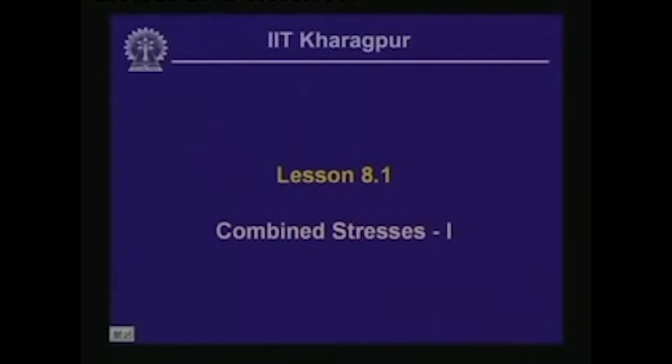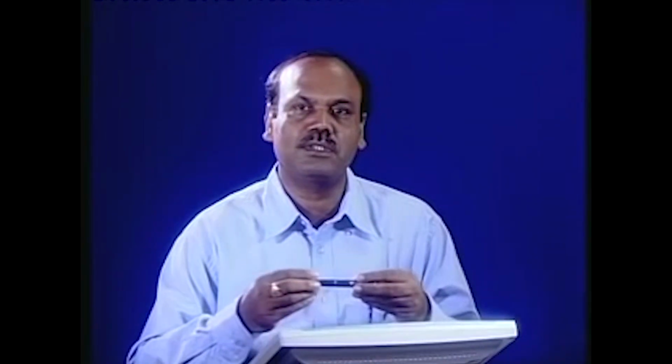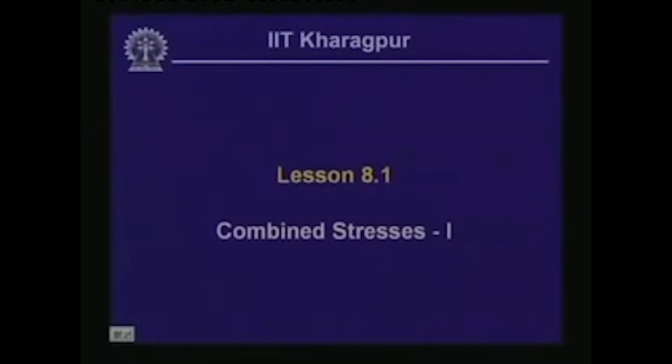Welcome to the first lesson of the 8th module, which is on combined stresses part 1, or more precisely let us call it the stresses which are developed due to the combined actions of loading in the members. In fact, so long we have discussed the action of different kinds of forces in the member which are acting in an individual form. For example, when we discussed the axial force in a bar, the force was acting normal to the section and we computed the corresponding stresses which we called normal stress.